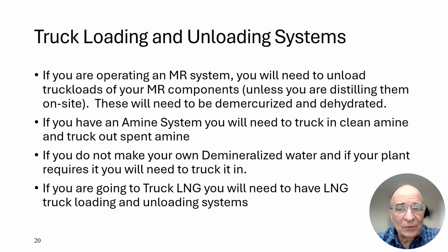Truck loading and unloading systems will be needed at your facility. If you are operating an MR system, that's a mixed refrigerant system, you will need to unload truckloads of your MR components unless you are distilling them on site. These may be ethane, propane, isopentane, etc. These will need to be demercurized and dehydrated before their use.